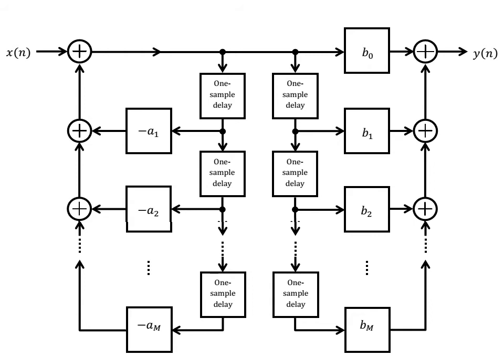And it corresponds to the first block on the left half of this is a feedback network, and the right half is a feed-forward network. So it's as if we're passing the signal x of n through one filter that in the transfer function gives us a denominator summation of terms, and taking the output of that, passing it through another filter that in the transfer function gives us a numerator summation of terms to give us finally the output that we're looking for, y of n.